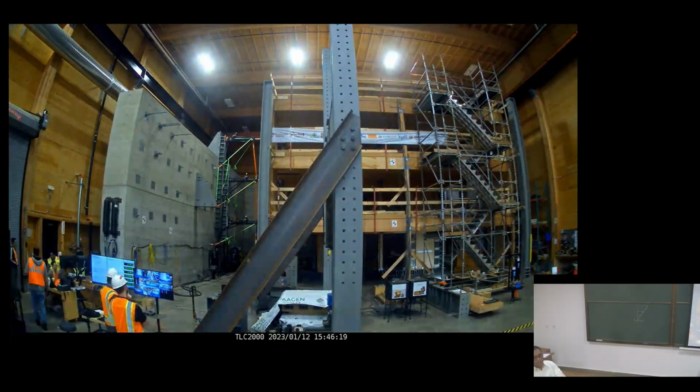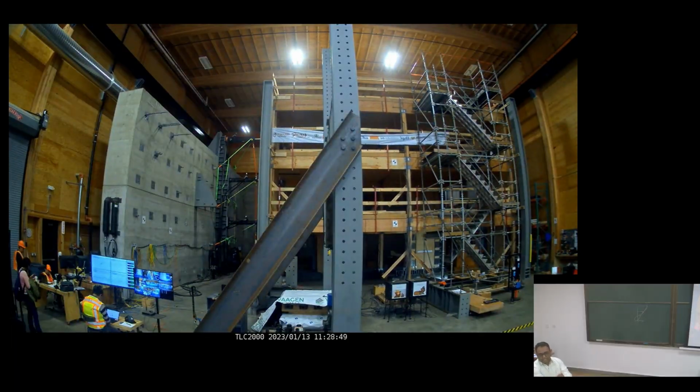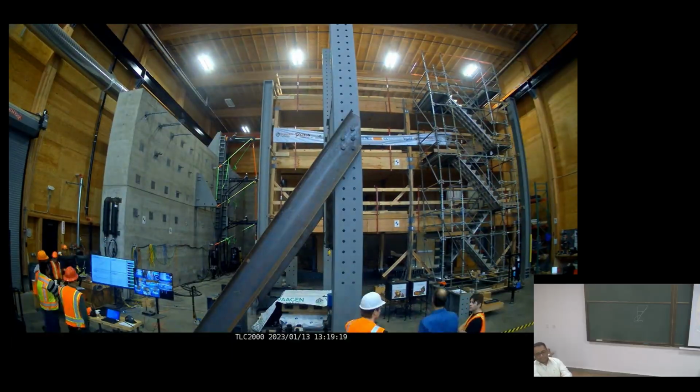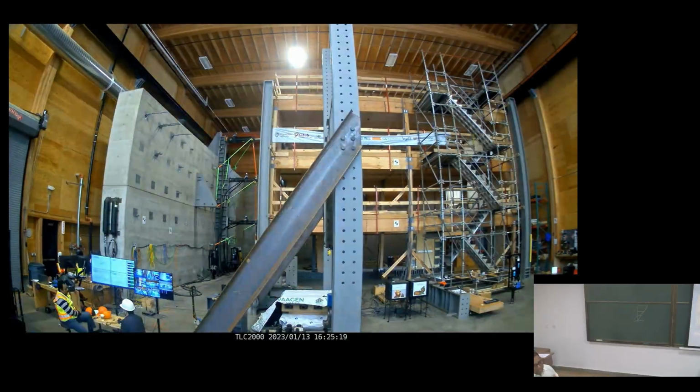After about 1% drift, we stopped. We took pictures, did damage assessment. After 2% drift, we stopped, and so on. We took our time getting as much quantitative as well as qualitative data as we could get from this test, because these tests, as Shrimali sir will tell you, are very expensive to conduct.